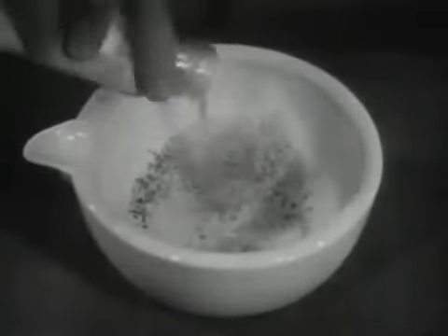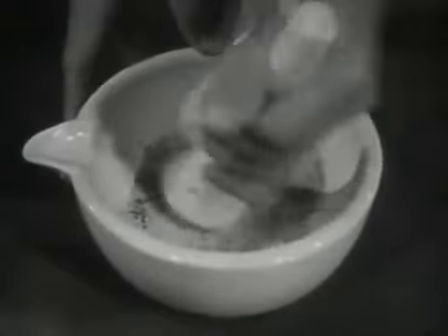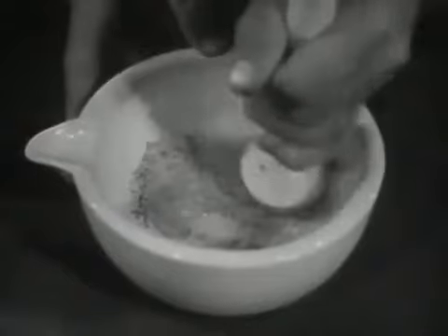Wood flour is also added to give the material the exact properties required. The resulting mixture is screened to provide a phenolic powder which is just right for the radio cabinet. Strong enough, the right color, proper heat stability, and so on. The cabinet is to be molded in a hydraulic press.